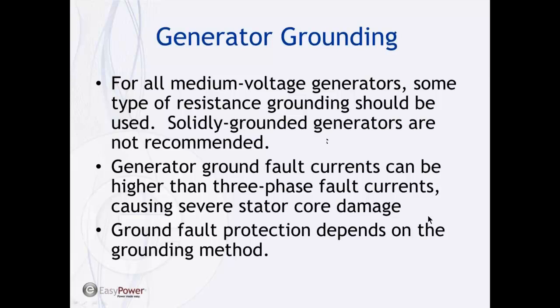Okay, so let's talk now about ground protection, ground fault protection, and before we do that, we need to talk about methods for generator grounding. And if we're talking about medium voltage generators, the recommendations of the IEEE and pretty much anyone else is going to be that you use some type of resistance grounding on the neutral of the generator. Solidly grounded generators are typically not recommended if you can avoid it. Some situations may be necessary to provide a ground source, but normally you're going to want to avoid solidly grounding the generator.